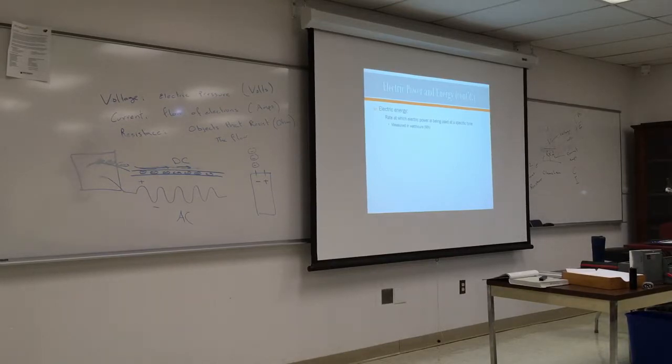So, two things you have to remember. Write the triangle, voltage on the top. That's Ohm's law. Second thing, make sure the units are consistent. You need volts, amperes, and ohms. What if you get milliamperes? You convert that to amperes. It's not going to be this for our field. We only deal with amperes, ohms, and voltage.